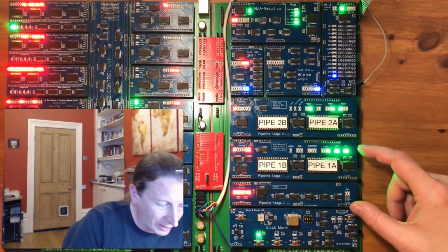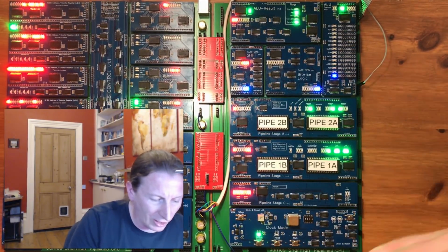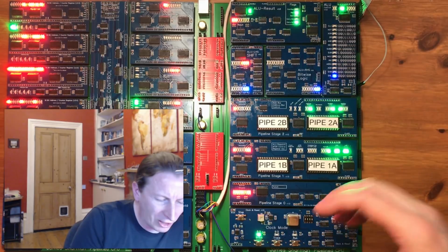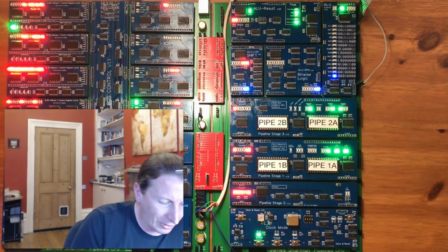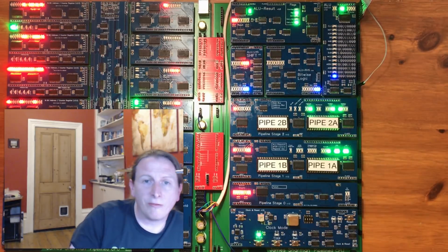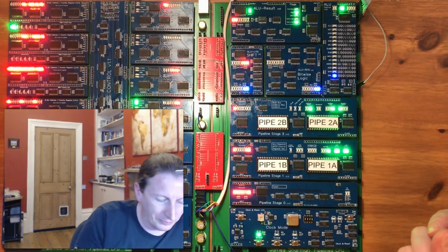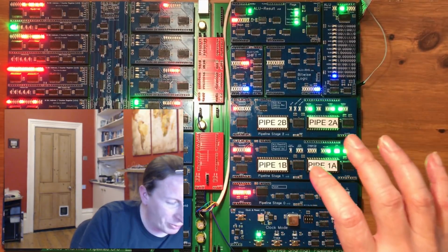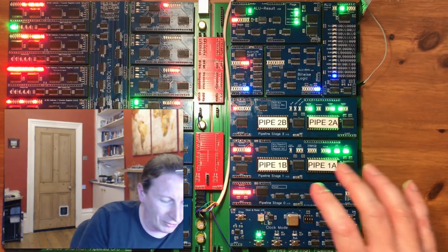The pipeline radically changes the performance profile of this compared to a stepped microcoded processor. So the kind of 8-bit generation of processors I've been most comparing to is the Z80 and the 6502. Now you can't 100% compare instructions per cycle. The Z80 roughly takes 4 cycles for each completed instruction. The 6502 is faster than that, but this processor gets very close to completing an instruction every cycle.